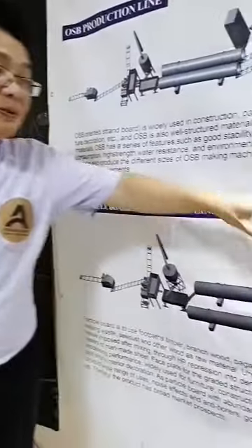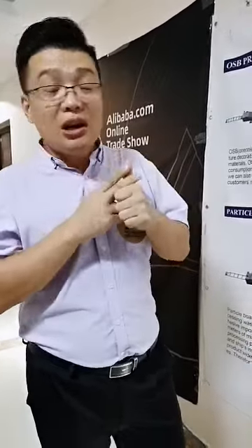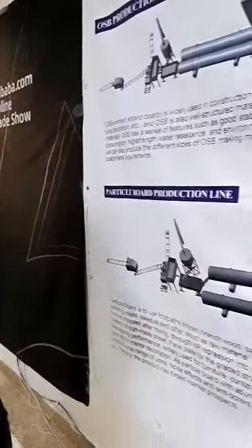And also, except for this kind of workers, you need an engineering group or training group. This must be about 5 or 6 persons. One, we call the production manager. The production manager must know the whole line's working conditions, and have knowledge about how to make plywood and particleboard, which kind of glue to use, what the solid content of the glue is, what the glue rate percentage is between the glue and the particles and the wood, and also how to control the moisture, the temperature of the hot press and the temperature of the drying.